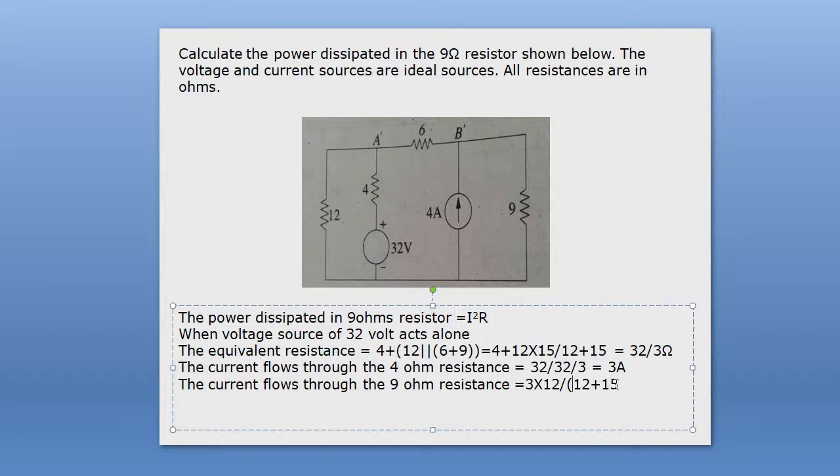everyone try to understand. If you have any doubt, let me know. Here you see that our objective is to calculate the current for 9 ohm resistance, but here we have written 15 ohm because the current flowing through 15 ohm resistance is nothing but the current flowing through 6 ohm and 9 ohm resistance. That means the current which flows through 9 ohm resistance is the same as the current flowing through the 15 ohm resistance. So therefore we can write this current value as 4 by 3 ampere.